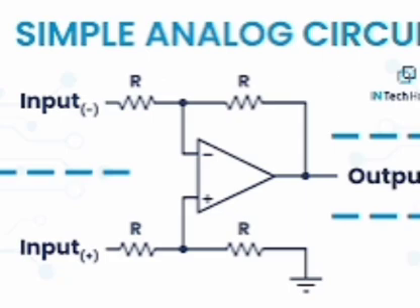Input impedance RI equals HI plus AI HR RL. Voltage gain AV equals minus AI RL by RI. Overall voltage gain AVS equals V0 by Vin equals AV times RI by RI plus RS. Output admittance Y0 equals H0 minus HR HF by RS plus HI, under the assumption RL tends to infinity and Vin equal to 0.